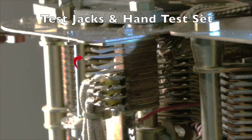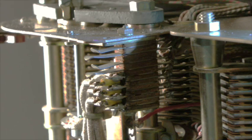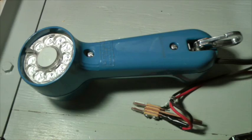Attached to the cover plate are these 4 test jacks. The top 2 jacks are extensions of the transmission path tip and ring leads that connect the line finder to the first selector. The top jack is the ring jack, and the second jack is the tip jack. These test jacks are accessed by the CO technicians using a test set like the one shown here.